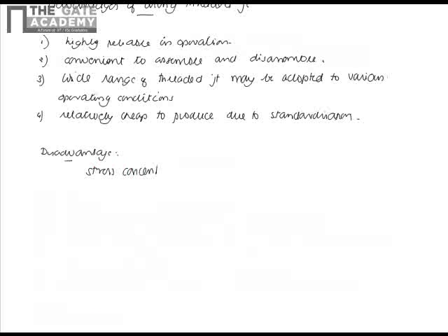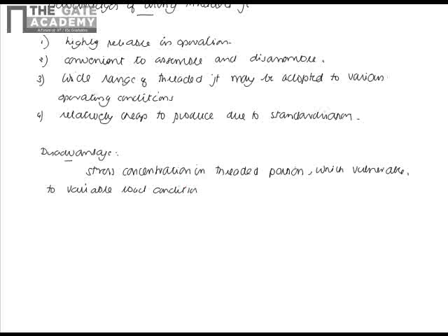This is a major disadvantage of threaded joints, and this becomes very vulnerable to fatigue loading or variable load conditions. Under fatigue load conditions this becomes very vulnerable because we have seen that stress concentration is a very important parameter which causes failure under fatigue loading.